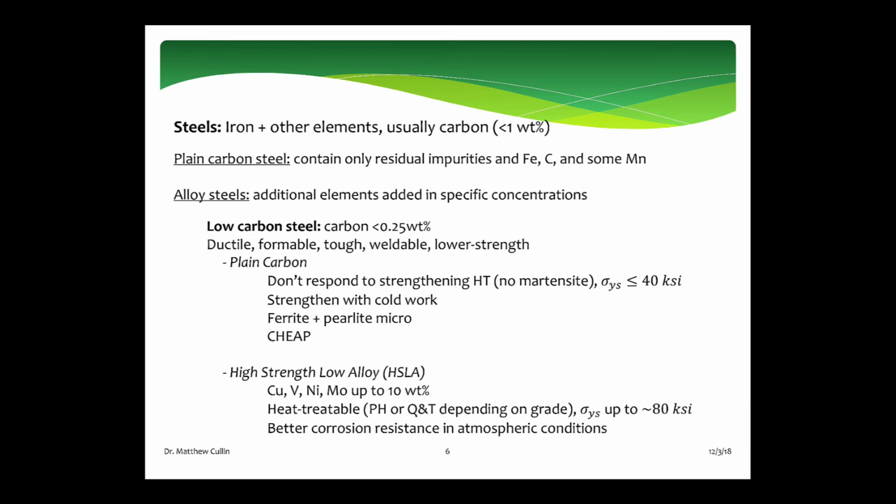And from your perspective, if you put one of these HSLA steels outside, it would still look rusty when you came back. The difference is that the addition of the copper, vanadium, nickel, and moly doesn't make them stainless steels because they don't have the elements to be considered stainless. However, when added in small quantities, they make that oxide layer, the normally just garbage, non-protective iron oxide, a little bit better.